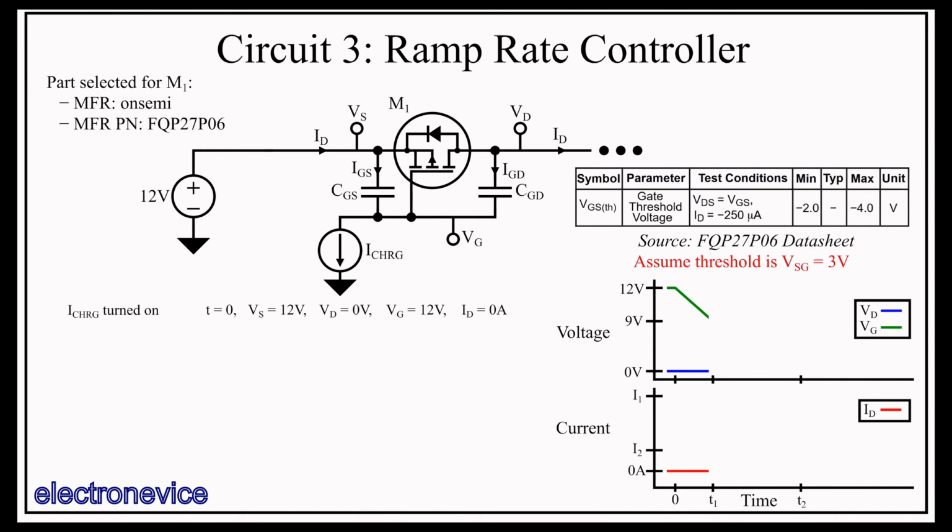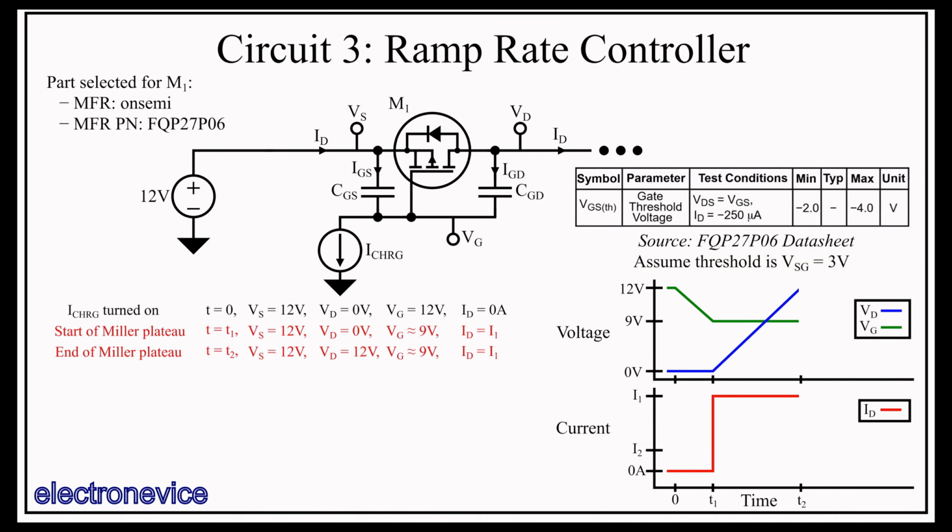This is only a rough estimate, and so will only provide a rough approximation of the results, but this assumption significantly simplifies this circuit and helps us to make a first-cut prediction of the behavior of the circuit. We can always refine it later. This assumption you're making is that, essentially, the transconductance of the MOSFET is infinity for VSG values greater than the threshold voltage. So now VSG is fixed, VS is fixed, and current is flowing through ID.